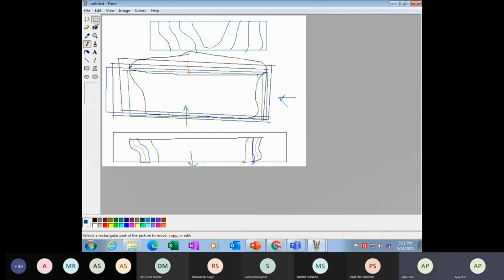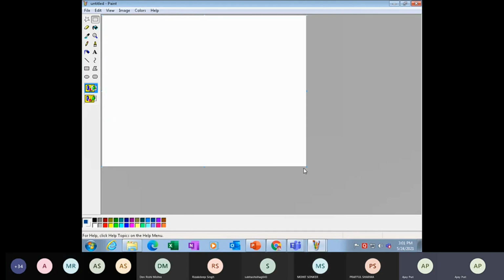Because a ship has to be made hydrodynamic, for that its block coefficient has to be set. A cargo ship's block coefficient will be very high, so it will not be too hydrodynamical like your VLCC. You can't attain too much speed because it has to carry cargo. So the main aim is not the speed but the cargo. In a container ship, the main aim is speed. It is the speed there. For that reason, they have to reach about 18, 19 knots or 20 knots. So we will make it more hydrodynamical.